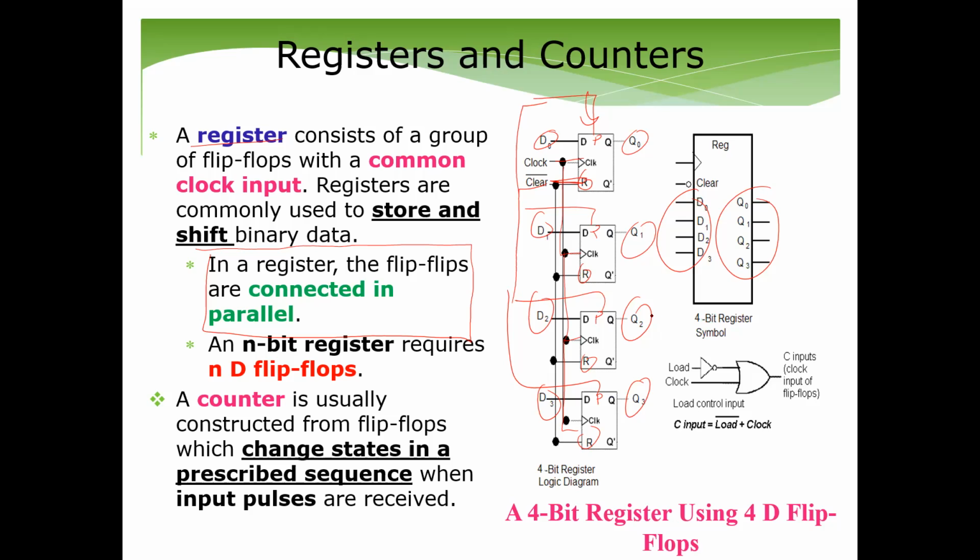Now, what do you need to create a register? You just need n-bit. For an n-bit register, you need n D flip-flops. If you want to create a 4-bit register, you need 4 D flip-flops. If you want to create an 8-bit register, you need 8 D flip-flops.